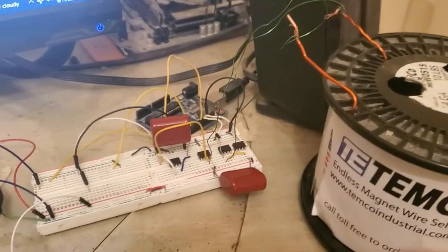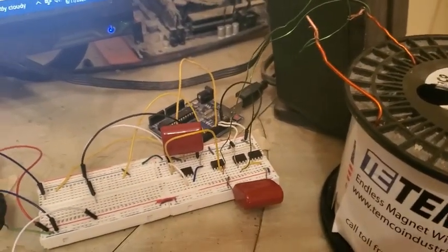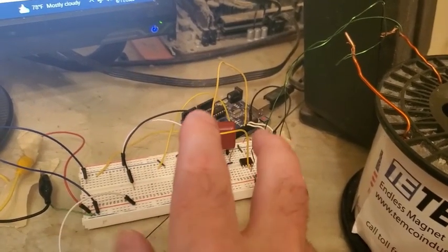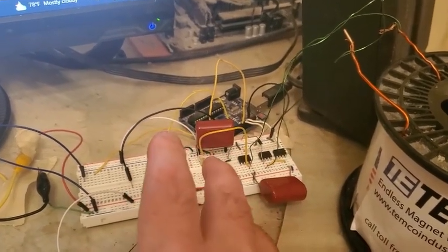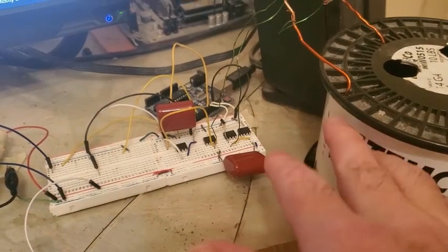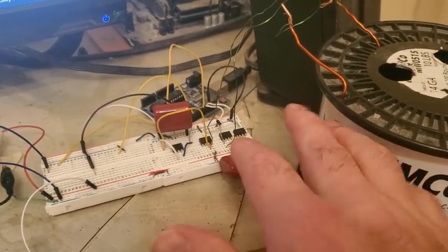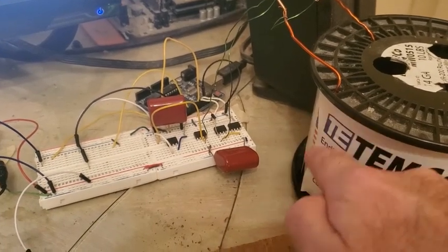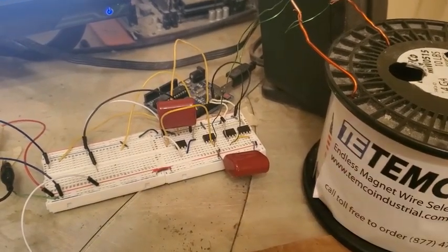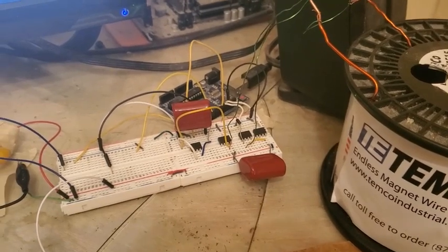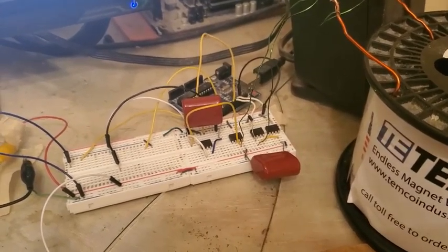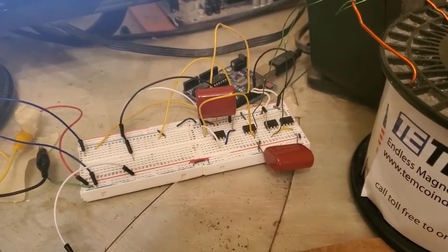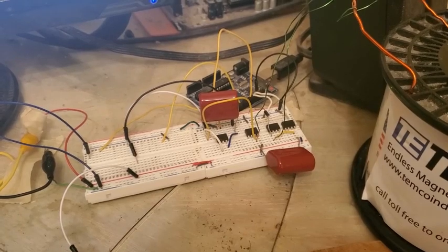Okay, I got a message that I ran out of storage space, so I think that's telling me something. But just to finish up, I was saying the third thing would be to do the synchronous rectification and see, can you gather the induction when the inductor is charging up as well as when it's collapsing. I don't know whether that can be done easily or not, but those are the things I'm going to look at going forward. And I think the first one is going to be trying to get an opto-isolated MOSFET.